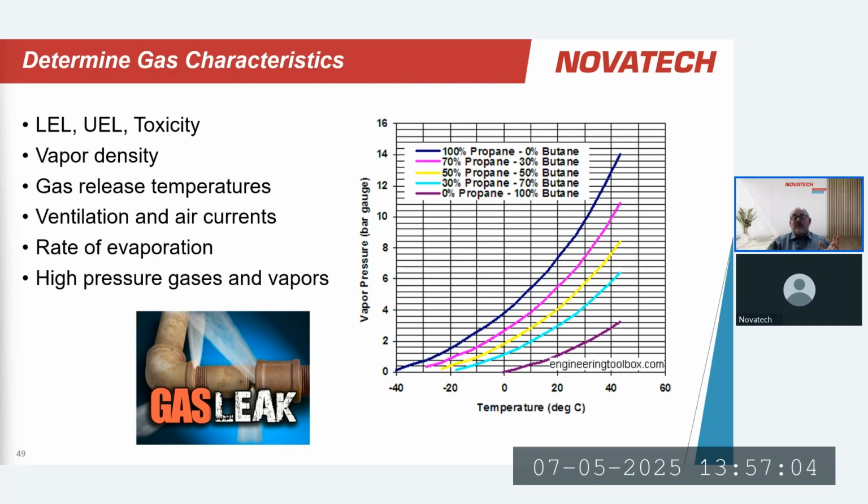But the hazard that's more likely to cause danger to personnel is the H2S. The H2S at 500 ppm could overcome a worker that opens the door to that cabinet and potentially knock him flat on the ground. So is an H2S detector the better approach, or a combination of both? Those types of things have to be taken into consideration.